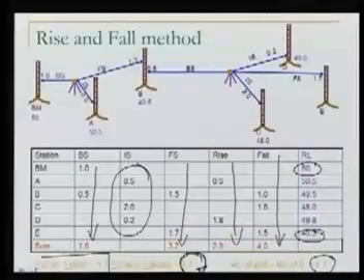So what we have done, unlike the previous method, the method of height of instrument, we have also now, because in rise and fall, the way we are computing them, we are including the intermediate sights also. So we are applying this check to the intermediate sights also. If any of the intermediate sight computation is done wrongly, we can have a check here now. So in that respect, this is a better method.